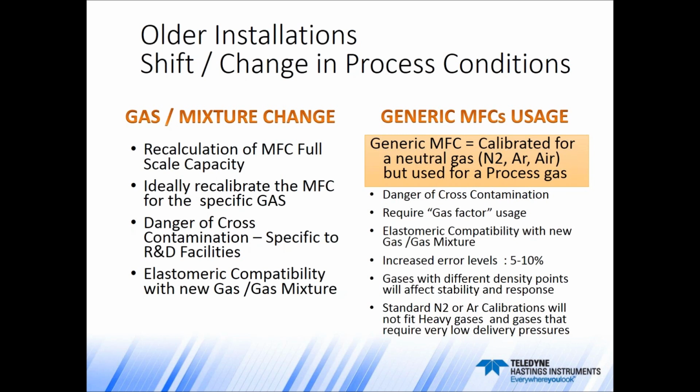As Doug has pointed out earlier, gases with different density points will affect stability and response in the usage of a generic MFC. And also standard nitrogen or argon calibrations will not fit gases, heavy gases and gases that require very low delivery pressure. So you will see instability in flow and possibly those particular flow controllers not being able to reach full scale consistently during process.